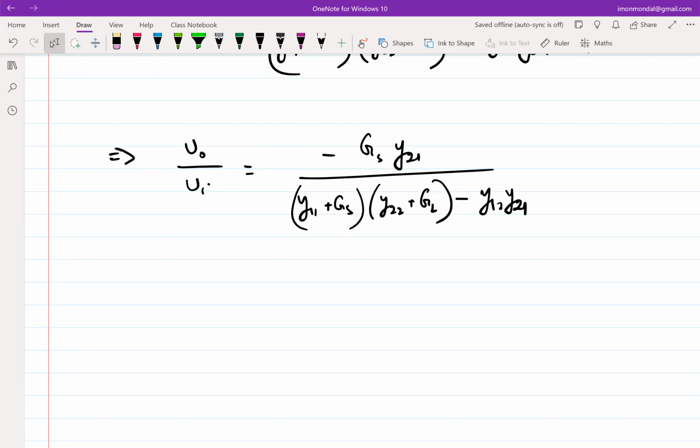So if I have to maximize the voltage gain, what do you think? What is the easiest way to do? Minimize the denominator, and assuming again further that all these incremental y parameters are positive. By the way, they did not necessarily have to be positive because they are derivatives of a certain curve. So they can also be negative. But let's assume they are positive for the time being. If they are positive, then it's possible to null out the denominator by choosing appropriate values, right?